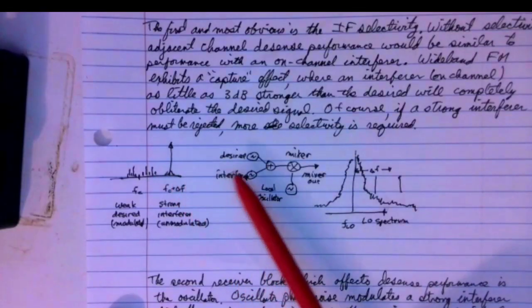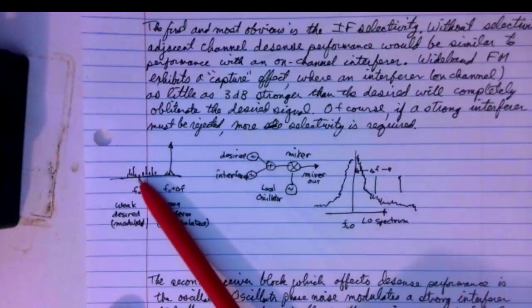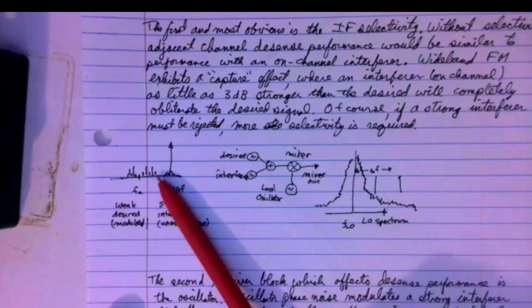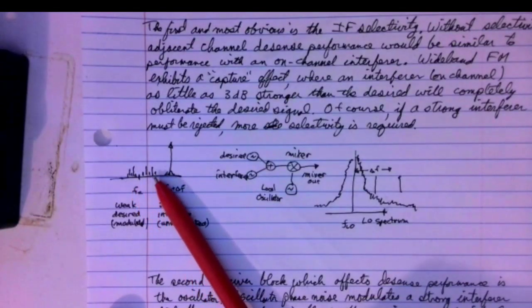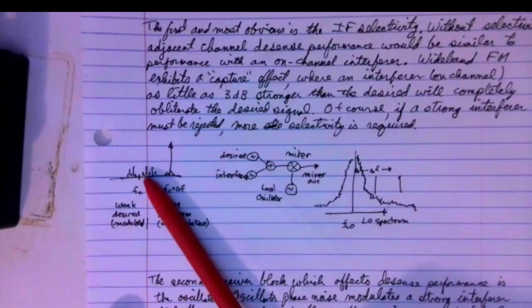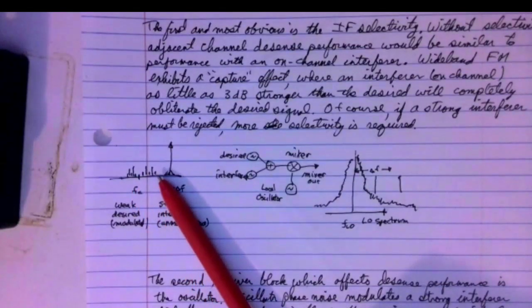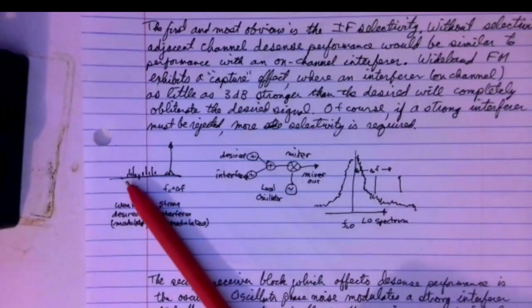And then the desired signal is a weak signal that is FM modulated. And so it might look like this, kind of. All right, so it's spread out over the allocated bandwidth. And you notice you don't see any carrier there, because the energy in the carrier has been distributed across the band, because FM is a constant power modulation technique.